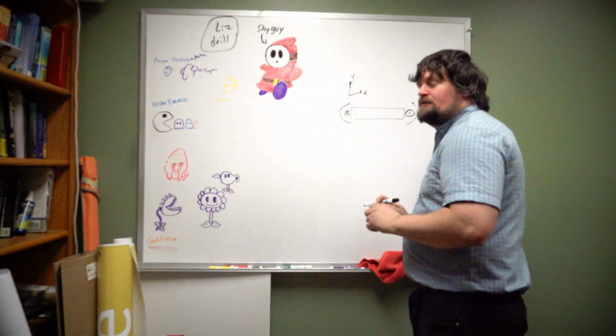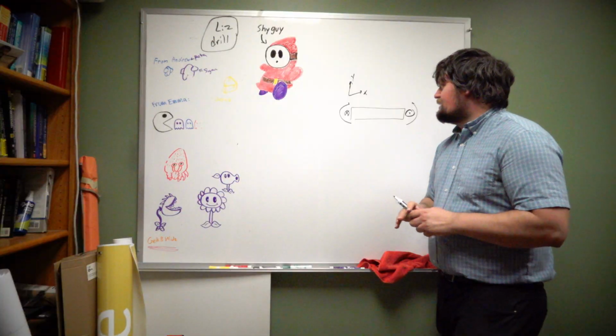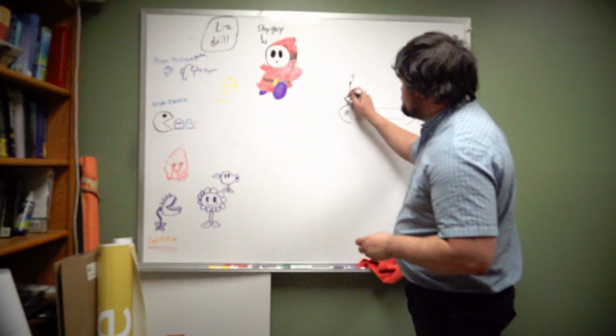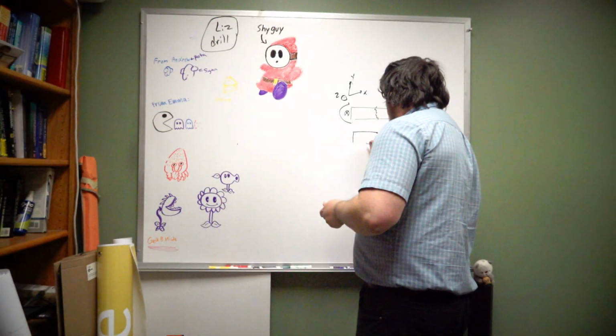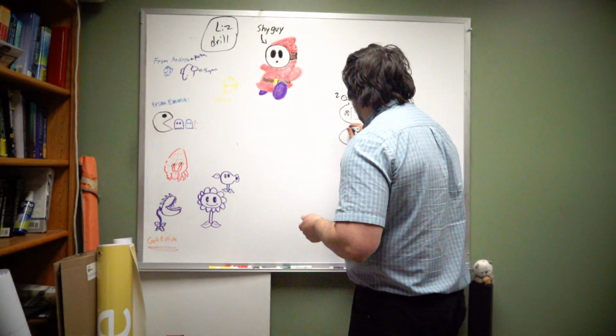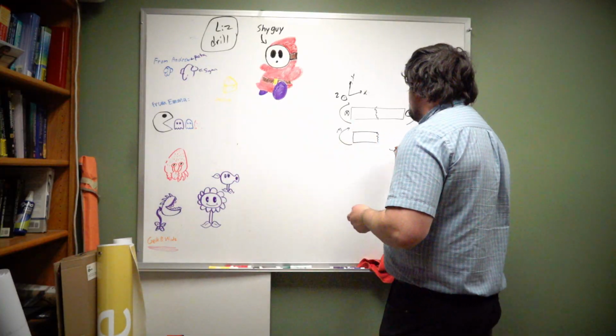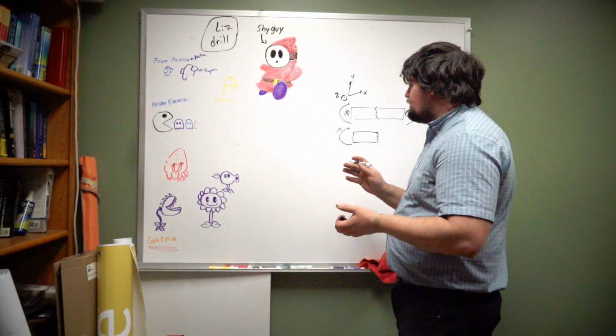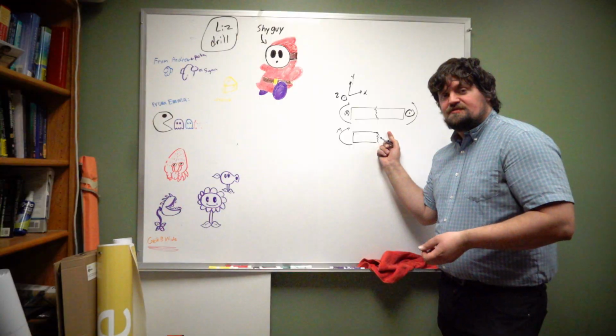We'll then draw this in the X and Y directions with Z positive coming out of the board. Okay? So this is what we're dealing with here. Now, just like what we did with the other two profiles, if we were to break this in the middle here and look at it so that it is broken here, we have this moment here, M. In order for this to be in equilibrium, we have to have an equal and opposite moment over here.